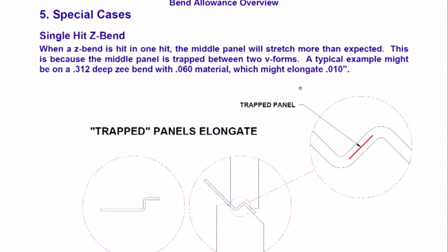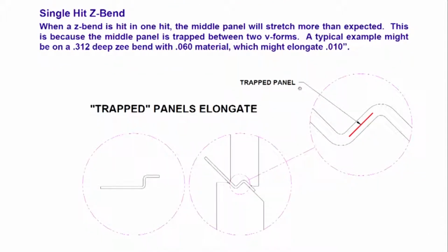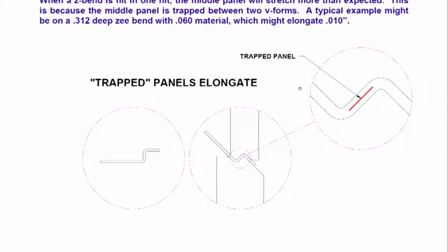I think correspondingly you may have to calculate the length that is there. This is in relation to the bending machine we have, which I have shown you in the video. In the bending machine we have fingers, and the clamp part under the fingers does not change in length. And then to accommodate for the internal radius, we also mark 0.5 mm inside.